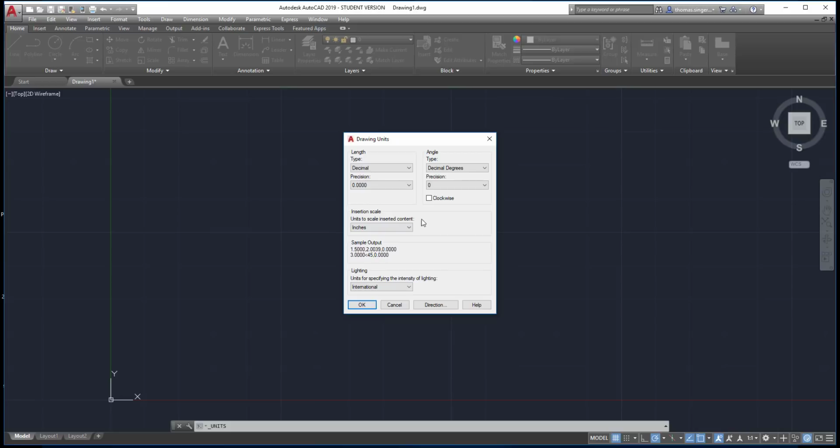From there, we also have the ability to change our style. Architectural units are in precision of feet and in fractional inches, and we can have different levels of precision. Well, if you're dealing with framing construction, if you have a 1/2 inch precision, you're doing pretty good. You kick it with your toe and it's close. But a 1/2 inch gap in a cabinet or between cabinets is unacceptable.